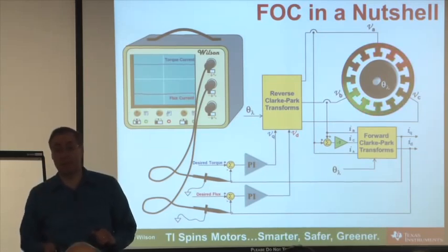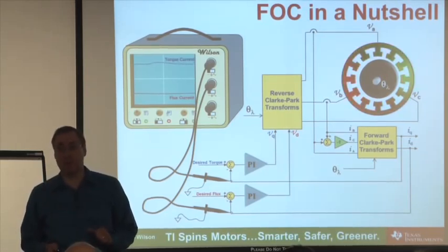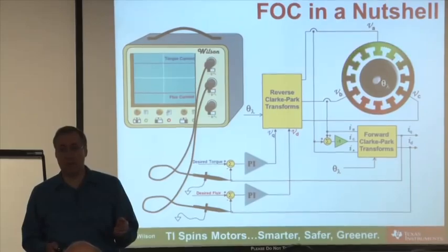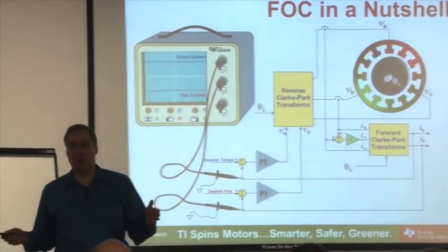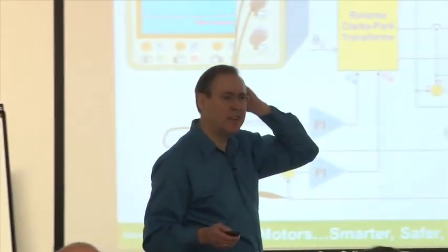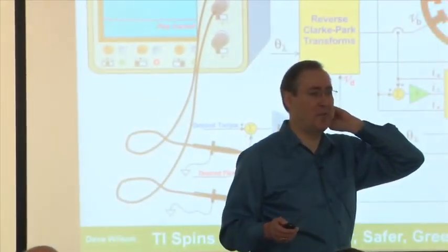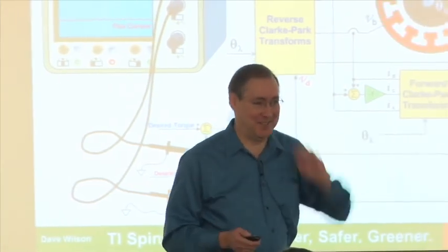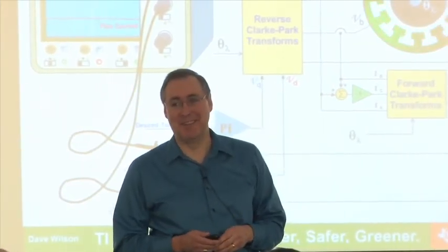Yeah, the same would apply to PWM resolution. Yes, that's something that most people forget about. Your PWM resolution can also have a problem with that. We do have an enhancement to our PWM module called the high-res mode, where I'm trying to remember. I'll get one of our hardware guys to answer that. What is the resolution? It's like 150 picoseconds of resolution, which is pretty smooth. So you would never see that in a field-oriented system.